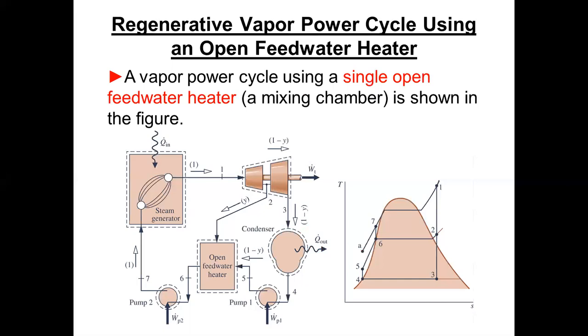Then if we trace the steam flow on around the cycle coming out of the turbine at 3, well, how much steam do we have? So we use these little symbols in parentheses, 1 minus Y, so that we can remember how much steam is flowing through the condenser. So if we had 1,000,000 pounds an hour out of the boiler, we only have 800,000 pounds an hour going to the condenser, which has to be condensed.